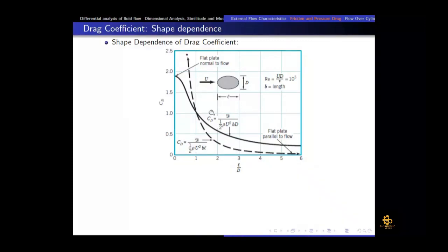But when we increase the length, it means that we are making a streamlined body, so the coefficient of drag reduces. Generally we know that if the body is thin, then the drag force on it would be less. That's why the aerofoil shape is a streamlined body type profile. Or if we talk about Formula One racing, we want to make the frontal area of the Formula One car very low, and it should be a little bit of a streamlined structure, so that we have less drag force on the car.